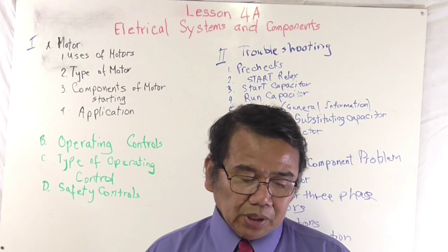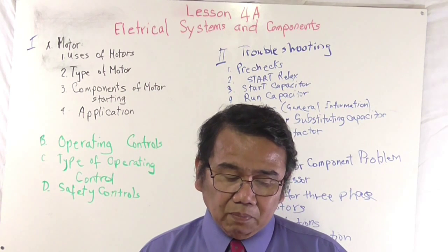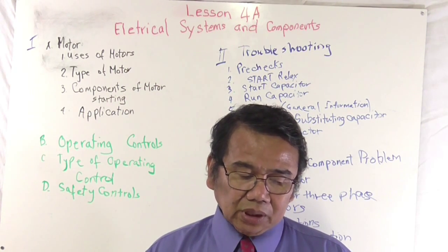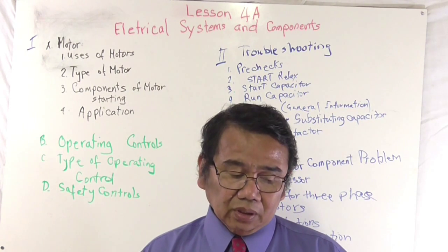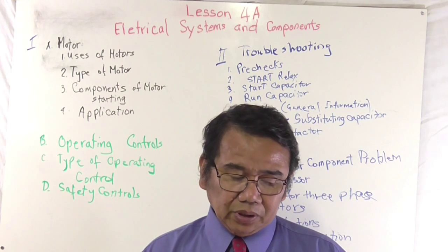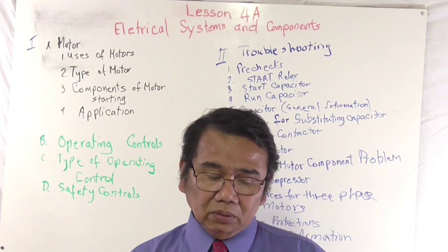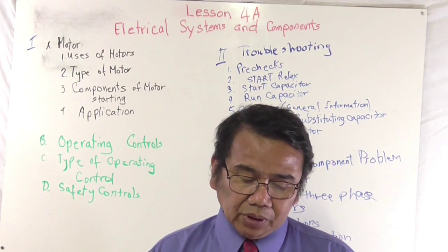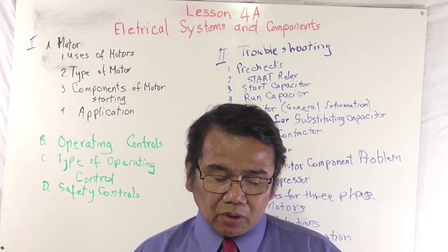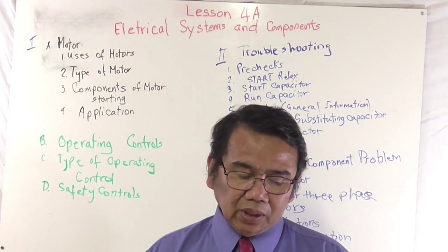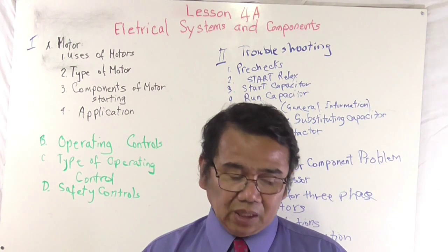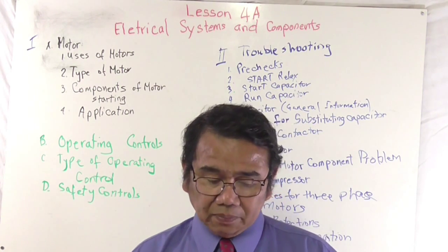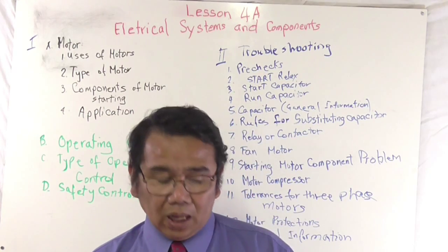And then you've got the potential start relay points stuck closed. The start capacitor stays in the circuit. It draws high amperage and trips the overload in about 10 to 30 seconds. Compressor will start but run with a loud growling hum. Eventually, the start capacitor will blow out.